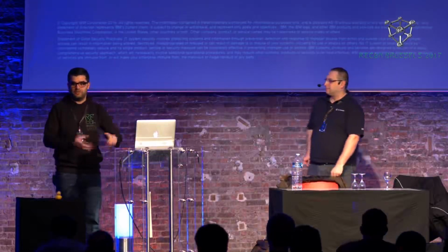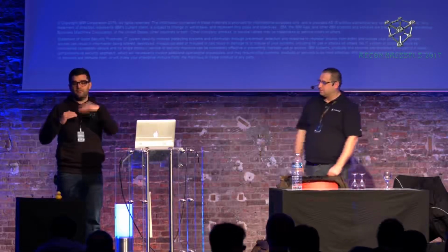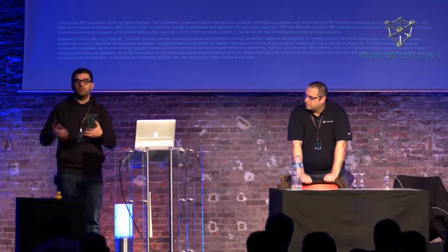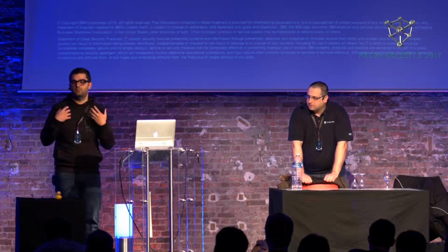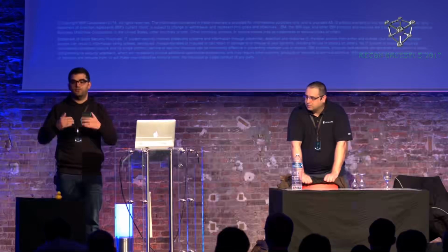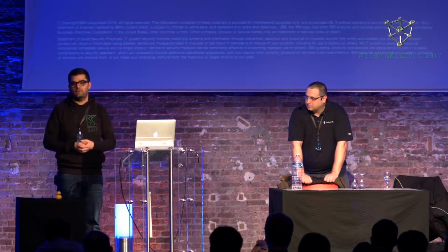So when we enable or disable interrupts, that's possible; the MCU will do that. However, you need to give it a priority. And there are certain priority levels, between 3 and 1, at which, even though you disable the interrupts, the core will always execute the handler, and even the RTOS kernel will stop executing that task. So when we say that we are enabling or disabling interrupts, we must be careful, because we cannot assume that it will happen in 100% of our code. If you have a task which is at 1, even if you are running something else, that handler will be executed when the interrupt occurs, even if you disable them. It's like a hierarchy, more or less.